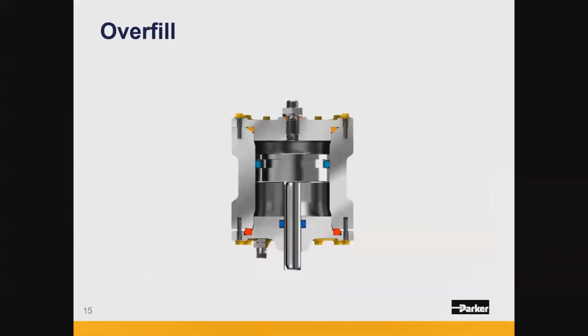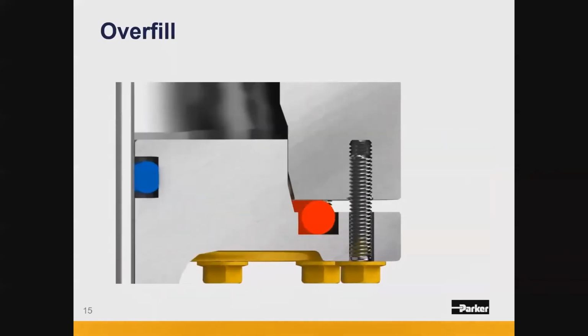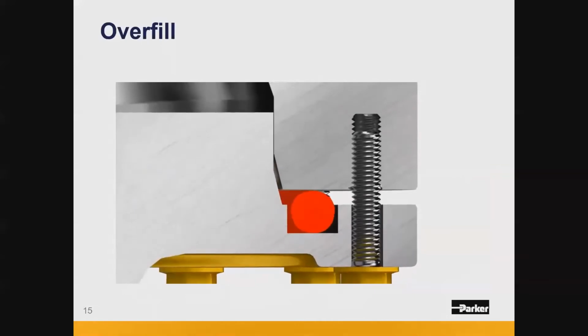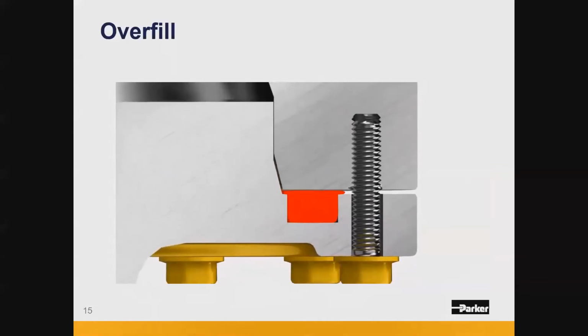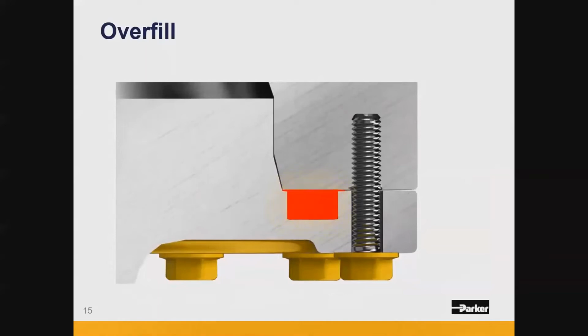This next slide here is a good animation of what this looks like in practice. So as the seal is compressed, you can see there's nowhere for the O-ring to go. The groove space is too small for the seal to be able to deform into it. So this is indeed a gland design issue because the gland is either too shallow or too narrow for the seal to be able to deform into without being pushed up into that gap between the hardware.